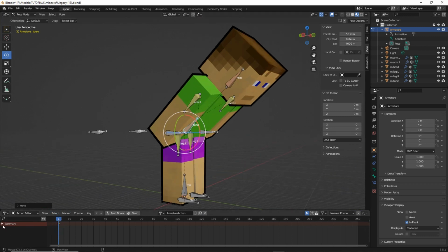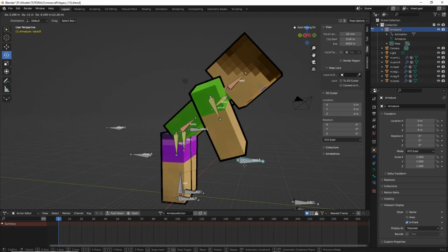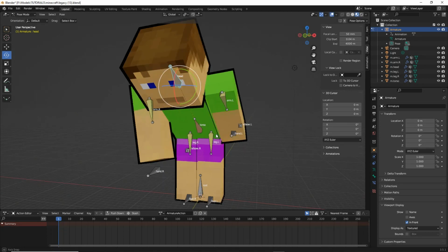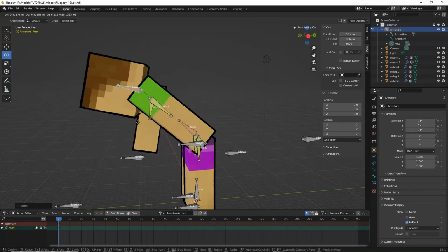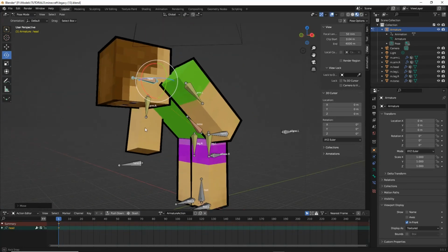There's one per channel, i.e. one per bone. So if we expand that, we've got our torso bone. Grab the hand, press the G key, grab the head bone, tilt that down, or we could press the G key and move that down as a group.